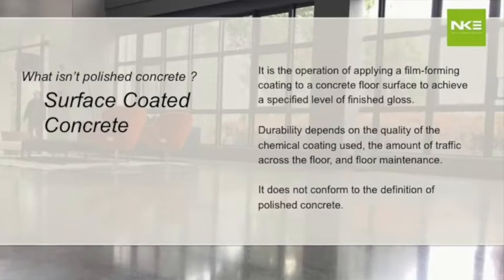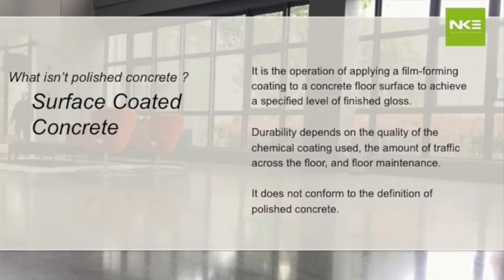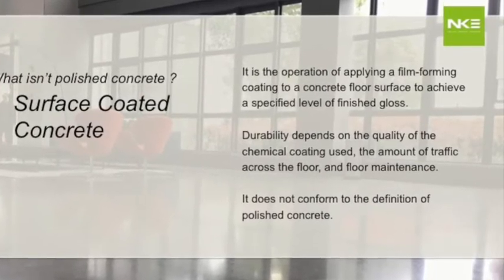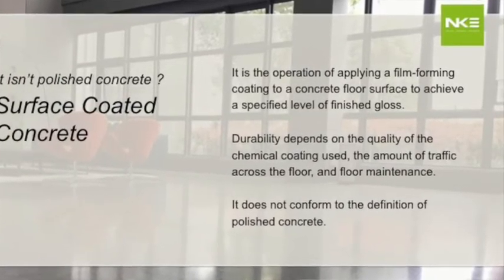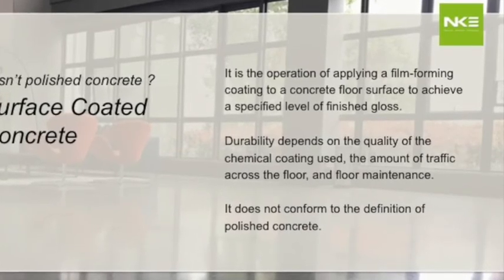And a not so experienced evaluator would assume that that's a great floor, but you should understand that that is not a great floor because you are just working on the strength of the sealant. So when the traffic is actually put onto the floor, if the sealant is not able to hold onto the traffic, your floor will again start getting exposed, and the floor will not perform well. So the sealant's purpose is to prevent penetrations, but not to give you a shine. The shine must be achieved mechanically.